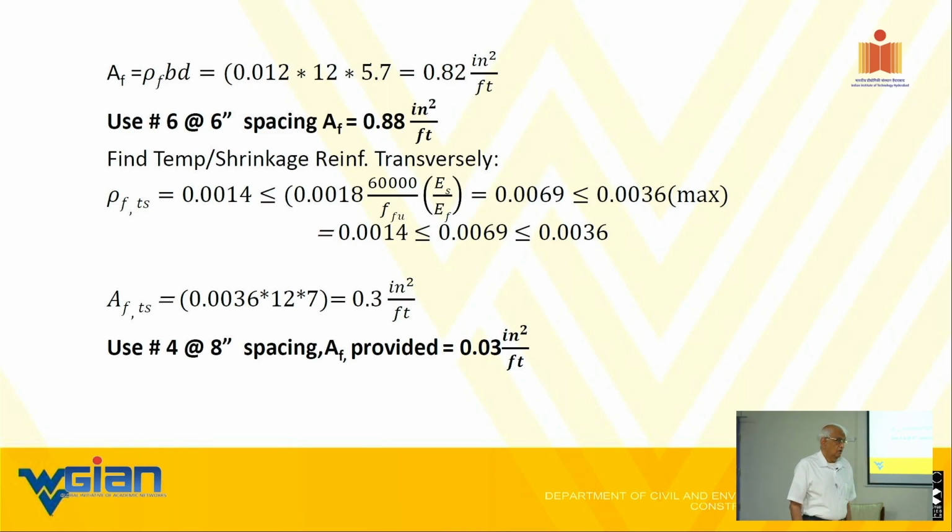70% of fly ash. And the only way you get the workability is by using the super plasticizer. See, have you done geopolymer concrete in the country today? No, I mean in the construction, I meant. Precast plants they're doing. Oh, good. Yeah, but not really the full-fledged; we cannot order concrete from RMC who will deliver a geopolymer. So what type of curing are you adopting for geopolymer? We are not adopting any curing other than ambient, that's it.